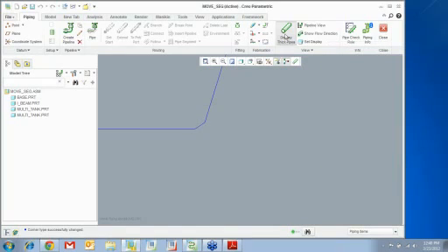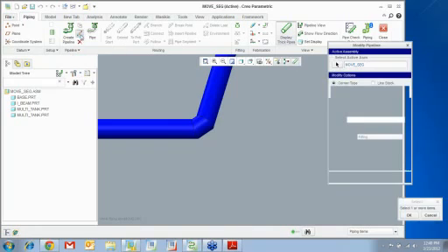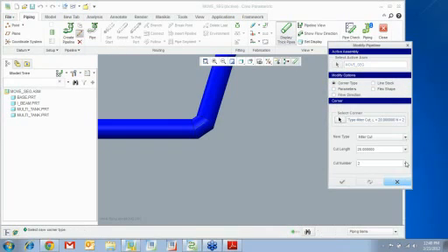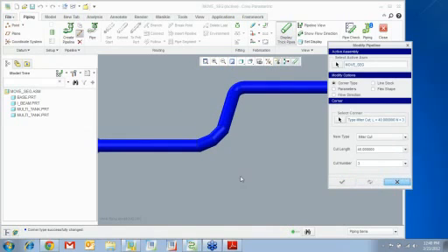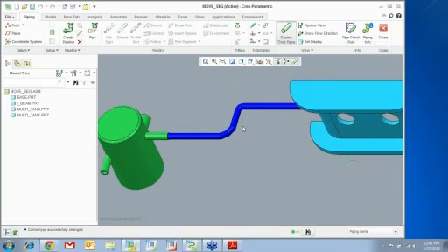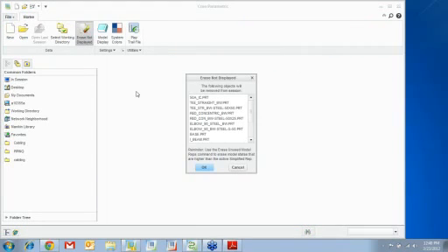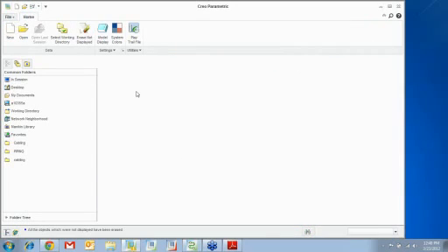And then you can do thick pipes. You can go edit, pick that, okay. I want 3 miters of 40 each. So you can see that, right? So you can edit all these within a pipeline real quick, okay. Now that we're done with spec-driven piping, we're going to talk about schematic-driven piping.